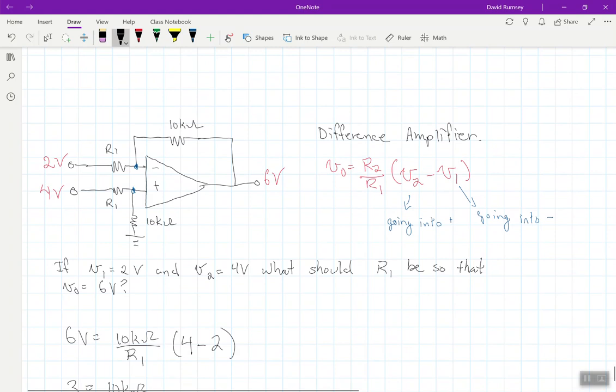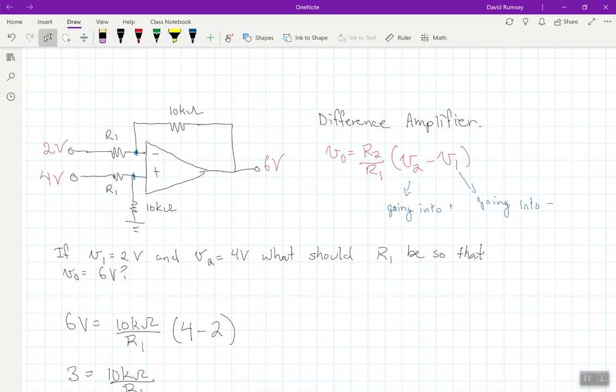So again, sometimes we need to determine what the resistor value is. And again, why do we want to do that? Well, I always like to look at things as far as debugging circuits. And sometimes, as silly as it might seem, there can be a wrong resistor value in there. Now, oftentimes the way you identify a wrong resistor value is either using the color code bars on it, or if it's a chip resistor, there's a number written on it which tells you what the resistance is.